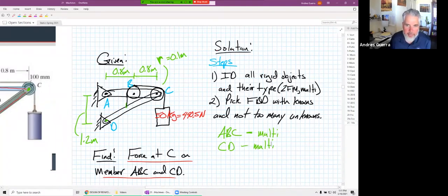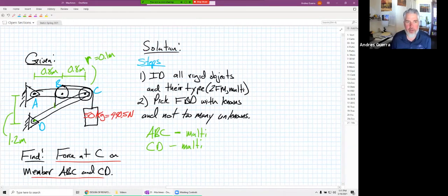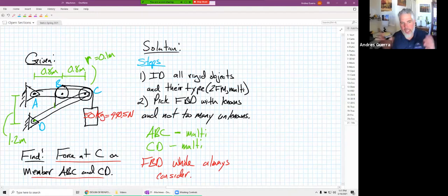We can do an FBD of ABC. We could do an FBD of C to D. We also talked about in that video that we could do an FBD of the whole thing. And so the whole thing is always another option for us. So the FBD of the whole, always consider for our problems, okay? So always look at that FBD of the whole thing. And actually there's a couple of different places to start with this one. I'm going to start with the FBD of ABC. And I'm going to do that for a couple of different reasons here. And when I draw this FBD, we'll talk about why.